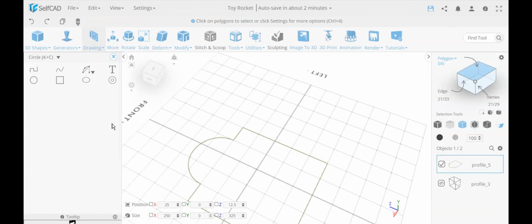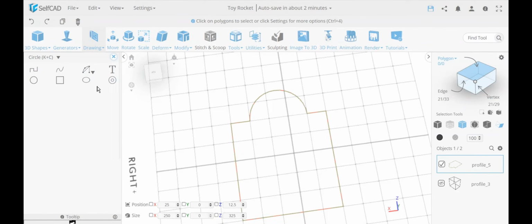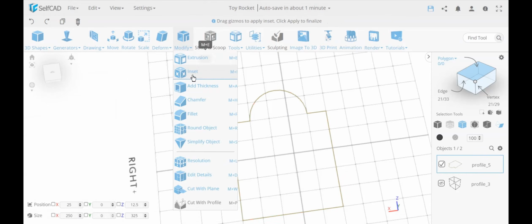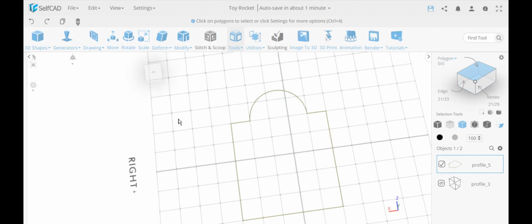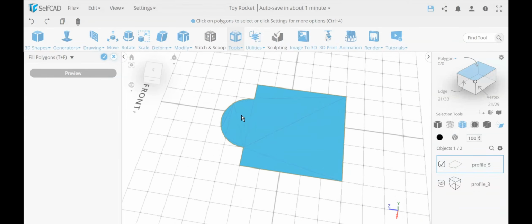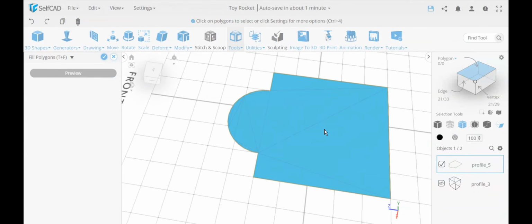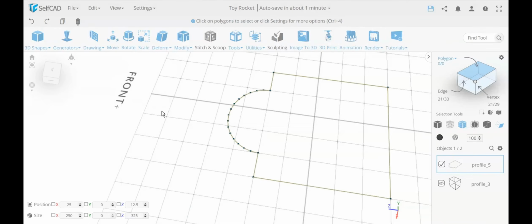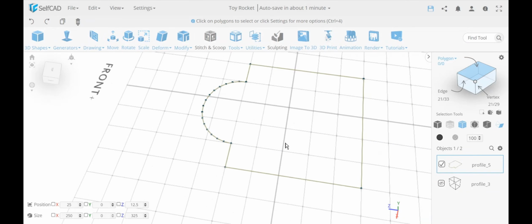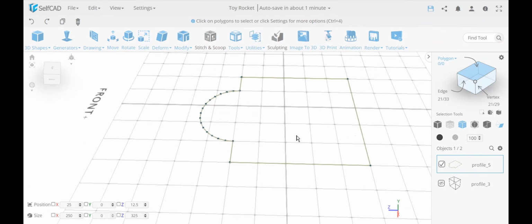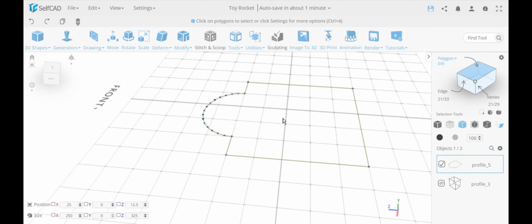Okay, so if I fill this, it's kind of a simple thing over here. If I fill this, let's use fill polygons to show it, but it's going to be the same way with extrusion. This looks like kind of an ugly triangulation. It's not really nice. So the idea here is that whenever you deal with this type of stuff, fill, polygon, extrusion, all of this, it's called a constraint triangulation. And this is very, very important because this allows you to mix and match, copy faces and stuff from other pieces of geometry, because what it means is that it always maintains the same amount of vertices. It can never add any vertex.